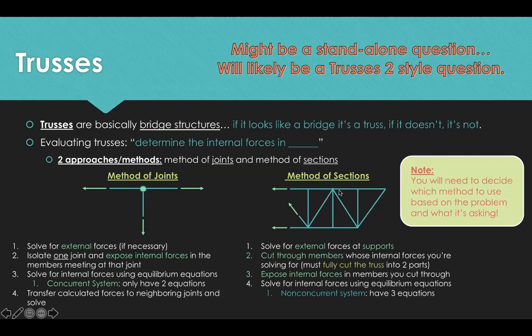That's a very good point to bring up. If you're looking at method of sections, or the three-member rule to find zero force members, you have to make sure that your force is going 100% through the joint, not through one of the members by association.